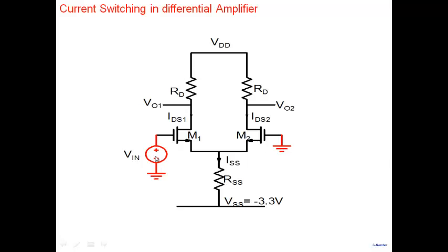One of the properties of a differential pair is that when you apply a voltage here, whether it's small or large, you can see its effect more in the large case. When you apply a voltage on one end, let's say this voltage is positive, and as we increase this value, you are increasing the gate voltage here. So it results in an increase in the value of this particular voltage here.